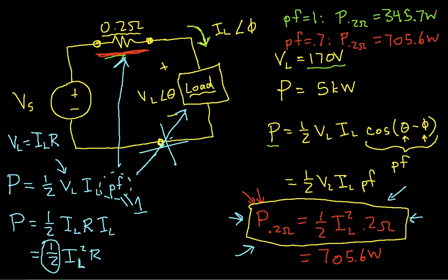We can use a similar approach to say that the average power is 1/2 times the peak voltage squared over the resistance. So again, it looks like the power relationships you're used to from DC circuits, but you've got this 1/2 here. And in another video, we'll talk about the idea of effective or RMS voltage that's been defined in such a way that you don't have to worry about the halves. So that concludes this video.